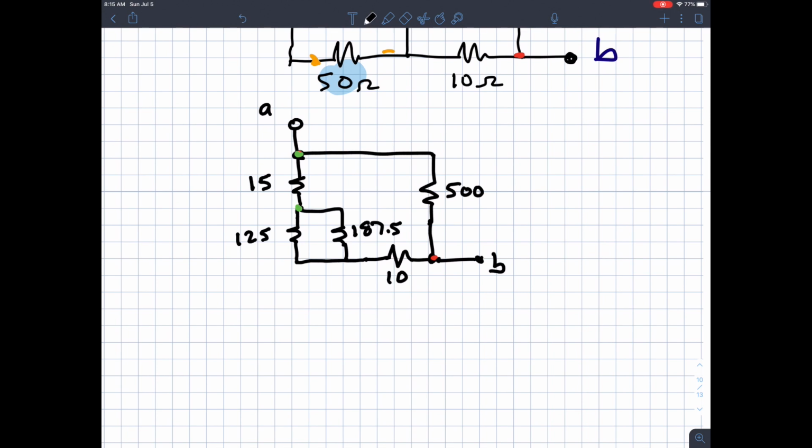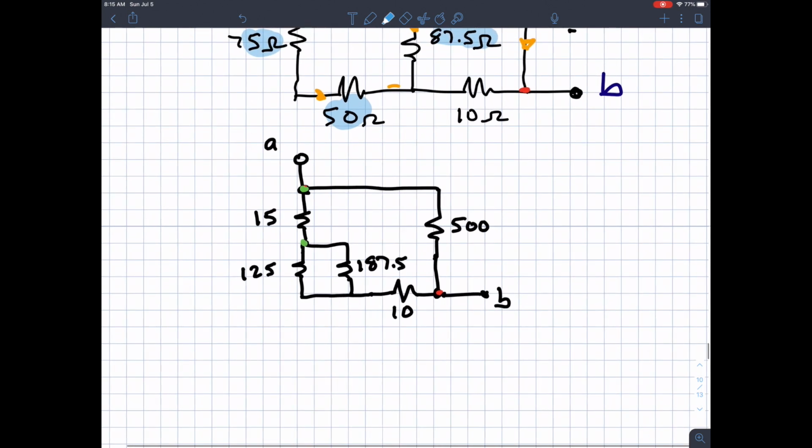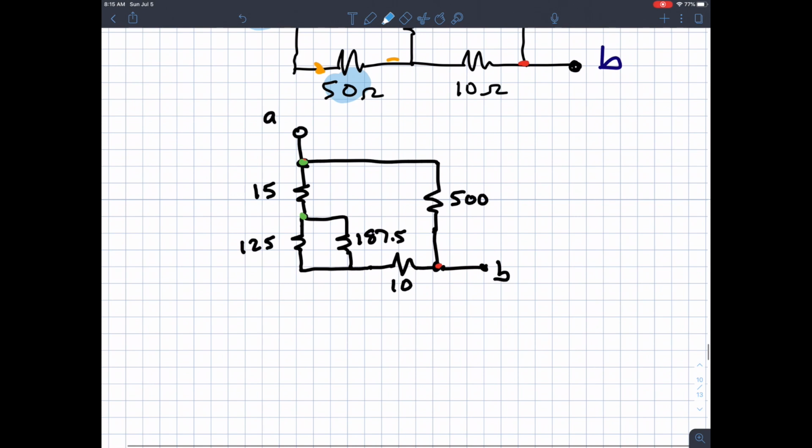they are in series, but you would have to rearrange these. Yeah, that would work. You could look at this and say the same current goes through the 15 and the 10, so you could move those to be in series and call that a 25 ohm resistor. All right, I didn't do that step. Let's just take it the way I see it next.